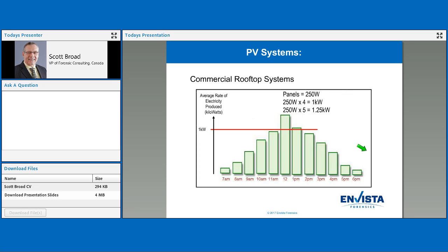In theory, I know this varies from place to place, but in Toronto, they have a tendency to overbuild by about 30%. So if they're looking for 1 kilowatt output, they will target 1.3 kilowatt output, so they're just going to add more panels and more panels until they can get that mathematical calculation. There are all kinds of algorithms that they use to figure this out, but ultimately this is what they call overbuild. You will rarely find an industrial or commercial build that does not involve an overbuild, because on the cloudier days they want to be able to generate more power.